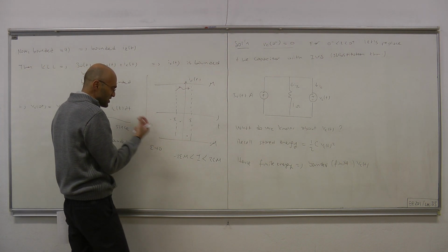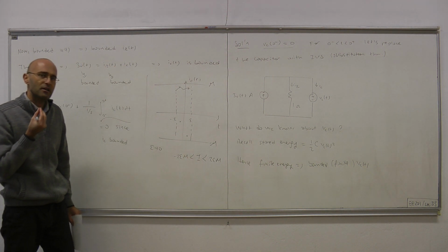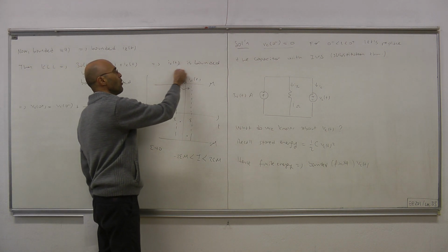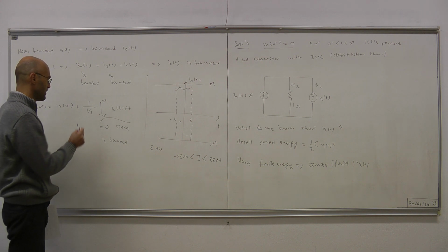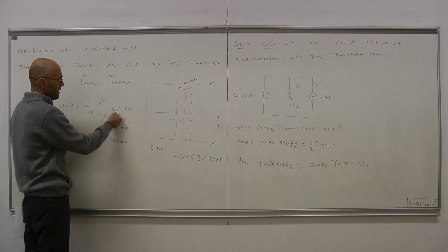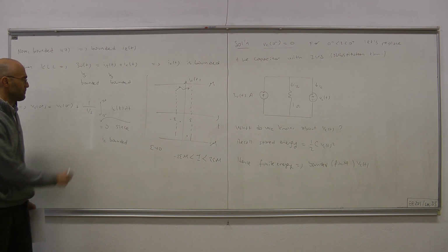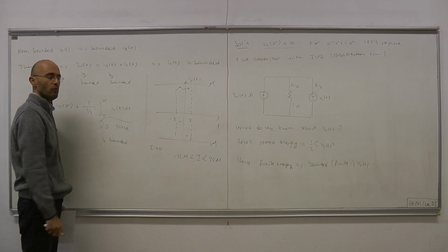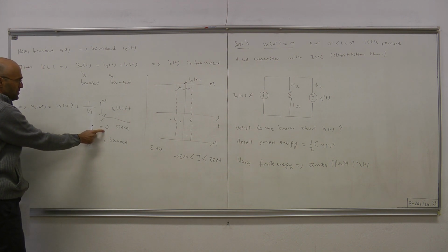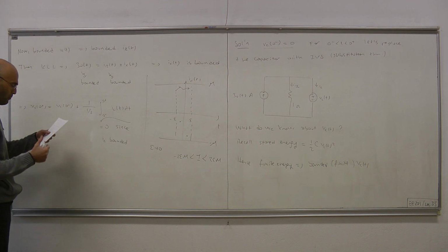Since it's fixed, at some point this epsilon becomes so tiny that this integral becomes arbitrarily small. And in the limiting case, it gives us 0. Therefore, once you know that the signal is bounded in some interval of length almost 0 or infinitesimally tiny, then the integral of that waveform throughout that special interval is always 0. Okay. So, since this is 0, that means Vc0 plus equals Vc0 minus.